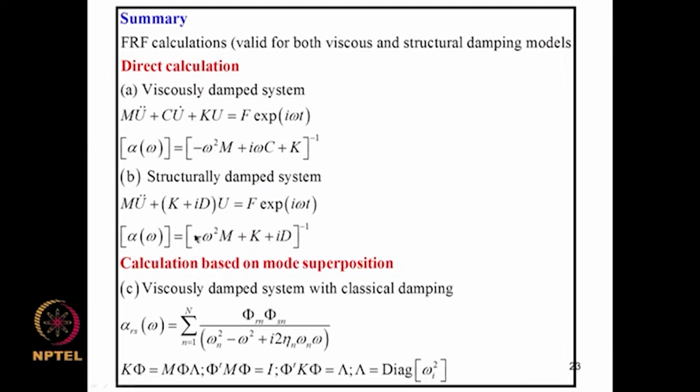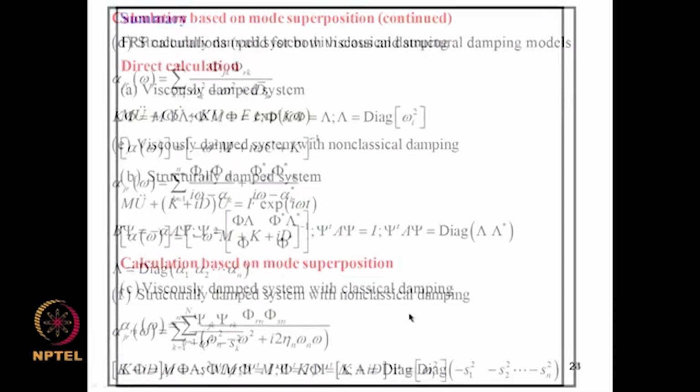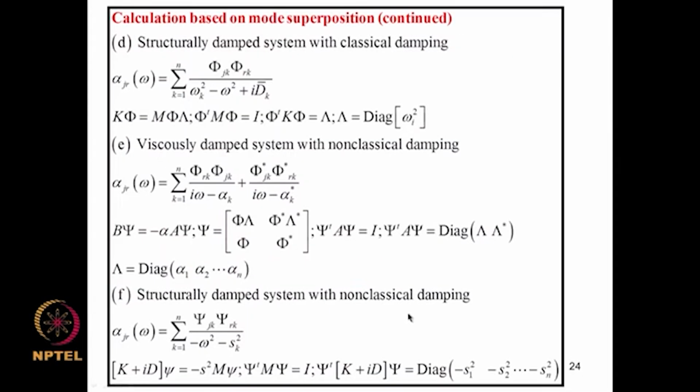But each one of these calculations can be carried out by using the mode superposition method, and that requires the determination of the appropriate natural frequencies and mode shapes. So, this we did for all the 4 cases of damping, that is structural, viscous, proportional and non-proportional damping models.